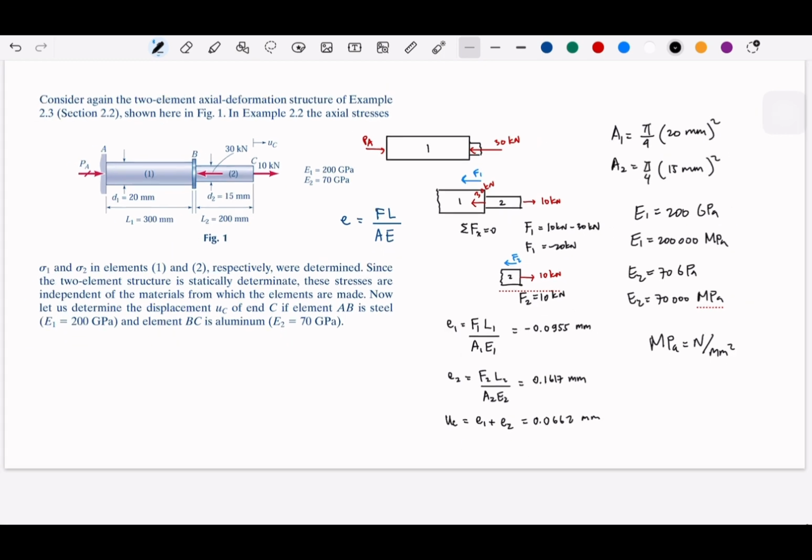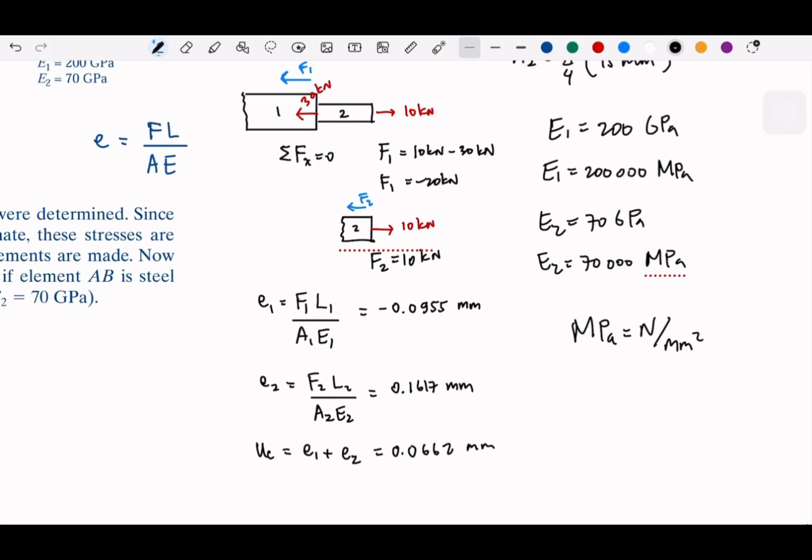So every time you have the total displacement, what you write is basically adding the sum of all these F L over A E terms, for however many rods or elements you have, and just adding all of this.